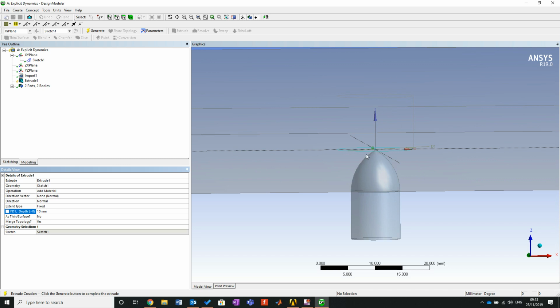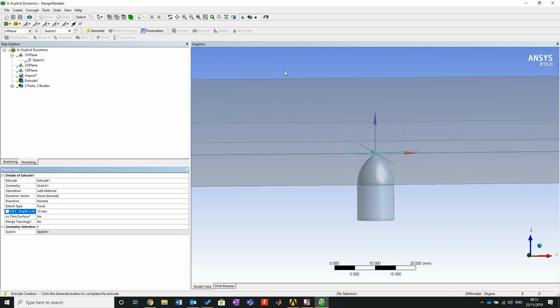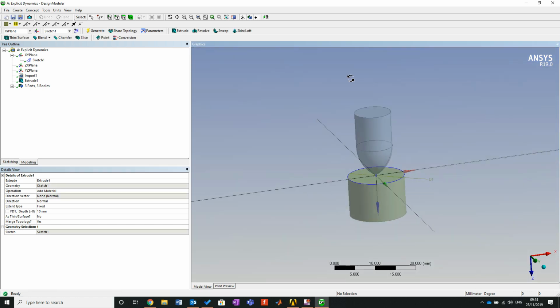Now the beauty with this is what we're using this for is a 3-component reference geometry that we can refine particular points on, to allow us to define when the mesh is going to deform in all different directions. So what I mean is this extrusion does not have to be as thick as the actual plate, because it's a component we're using purely for the meshing procedure, because these are going to become one, if you remember. So I'm going to click extrude. So we're then back into business.